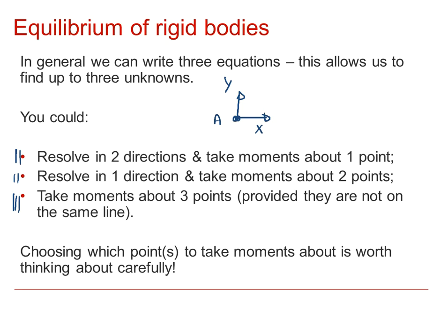And therefore, quite often what we do is take moments about a point where we've got lots of unknown forces acting, and those forces become irrelevant in the equation. And we'll see that in some of the examples that we're looking at in a minute.